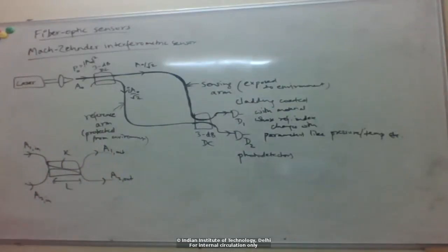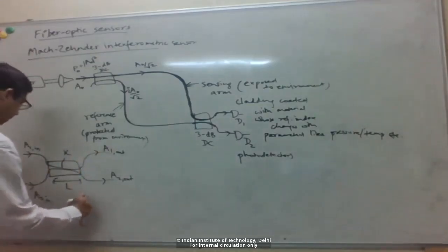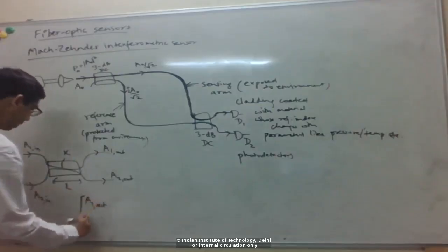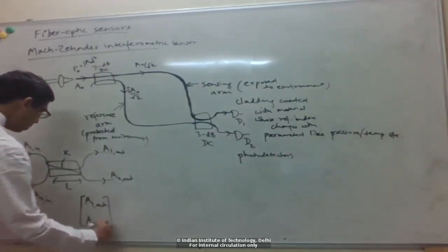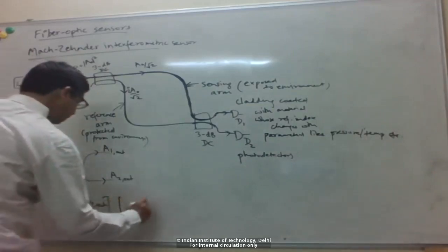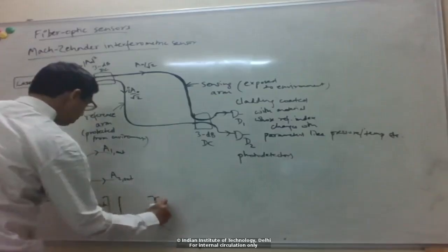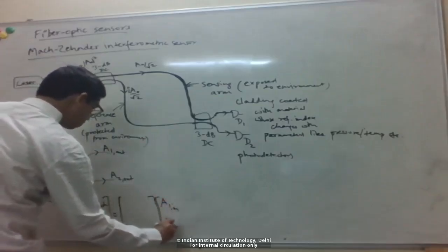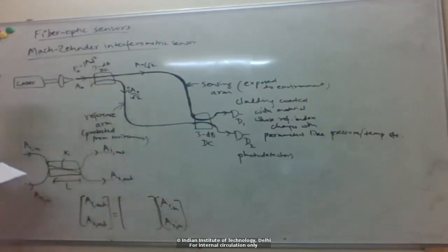Okay. So typically, when we discuss the directional coupler, we typically discuss the case only where we send in the input from one of the ports, right? But in general, I could have inputs from both the ports and also output from both the ports. Okay. So in this case, I would write my output amplitudes, right, as some transformation of the input amplitudes. Right, so this will be a 2 cross 2 matrix, right?